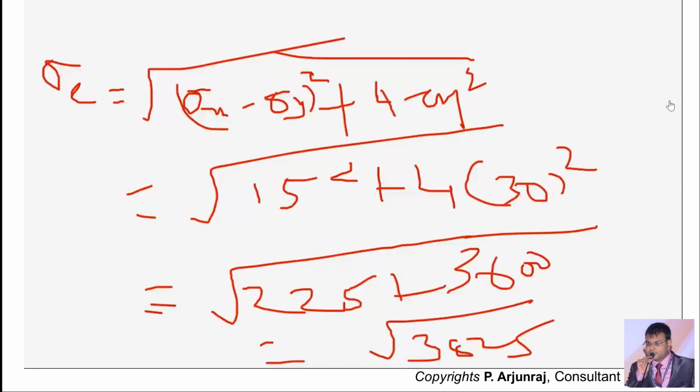Yeah, and the factor of safety is going to be 5.70. So the factor of safety using the maximum shear stress theory, or Guest theory, is going to be 5.7, and in the previous formula, using the maximum principal stress theory, or Rankine theory, we got the factor of safety as 4.23. Now let us go to the third one, as per the given problem. Okay, so I am going to the problem again.